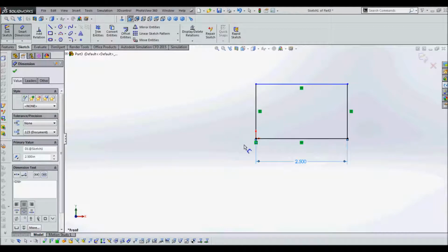If you need to change this, down here, slightly out of view of the window probably, but if you go down here you'll see a unit system selection, and you can set your defaults for whatever unit system is most convenient. For most of the things that we do on the team, we'll be using the IPS unit system, which is essentially Imperial, because it's most convenient to get those parts in terms of suppliers and things like that.